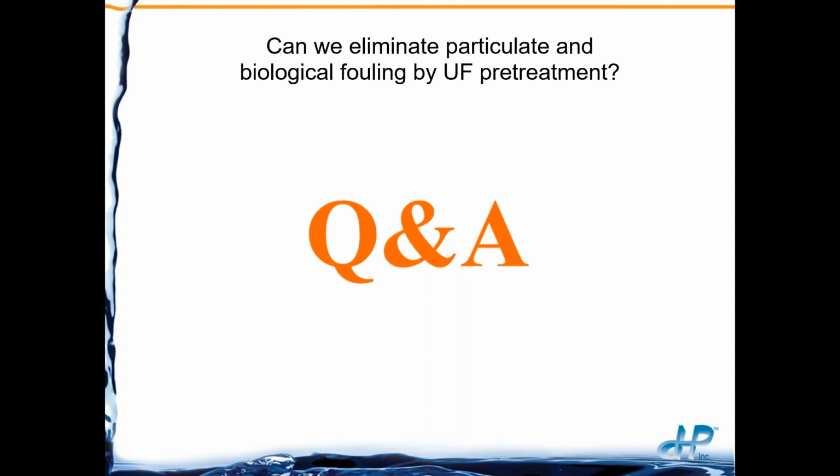Ultrafiltration, UF, has a 0.01 to 0.05 micron pore size, and so any particle greater than that will be filtered out by this ultrafiltration. The bad news is there's one contaminant that will pass right through an ultrafilter.